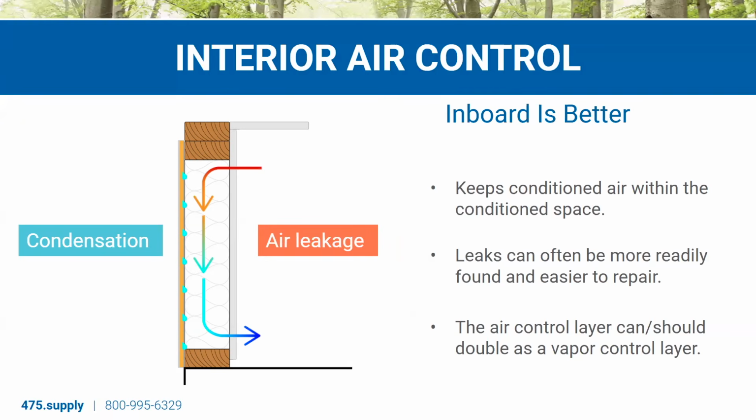This would all be flipped in our more humid or warmer climates, our climate zones 3 and below. Then we don't want our outside humid air moving through that insulation to meet our drywall that is being air conditioned where it's a colder surface. We don't want that warm air to meet it where it condenses. Again, we're just preventing warm air from meeting a cold surface.